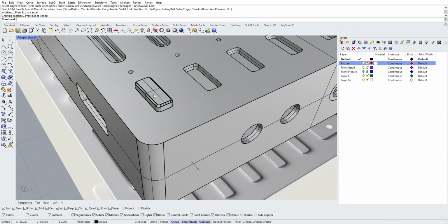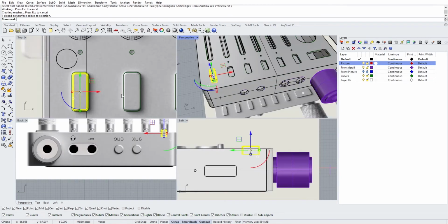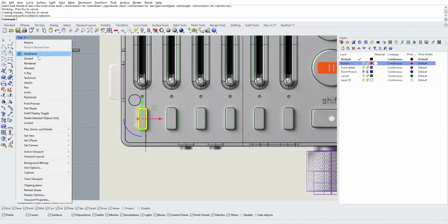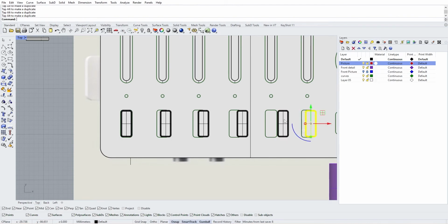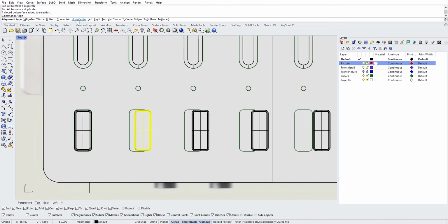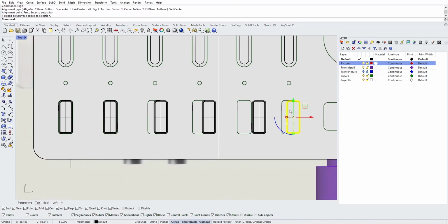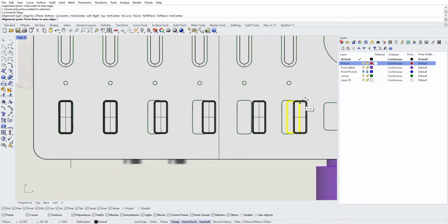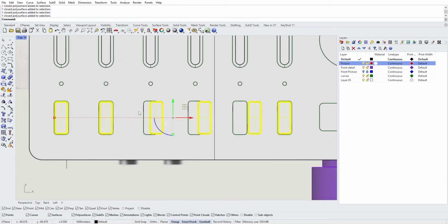So our button is created, so we can now multiply it to fill our holes here. So go from the top view, put it in shading mode, select your button, duplicate it many times, and then there are 2 ways to have it aligned. Either you align them individually with vertical center and here the center of the hole, or you align the last one here, so vertical center, and then you select your buttons and you use the distribute tool, on the X axis, like this.